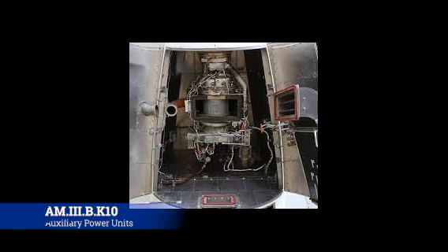Now, you're not going to get the full AC effect because you don't have the engines running that's going to run the passenger air conditioners or the packs. But you can get some air moving on the inside that at least helps start to kind of cool it off. And it gets your electrical power up to the point that you can actually turn engine one, turn engine two. It'll get hydraulic pressure if you need to run any kind of maintenance checks for your flight controls, all that good stuff. And that's all the APU effectively is.